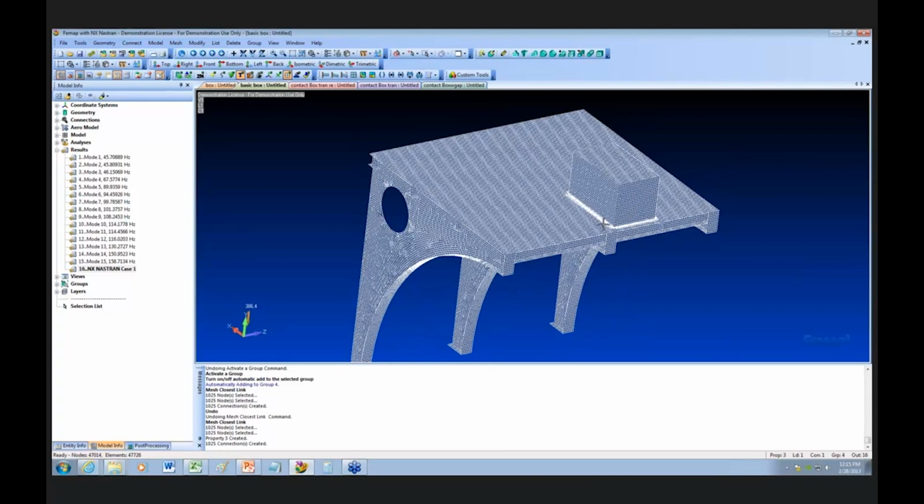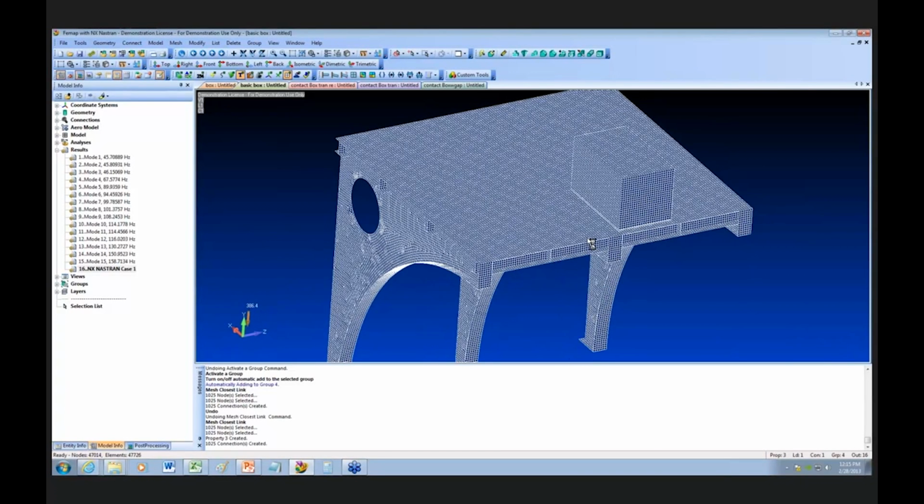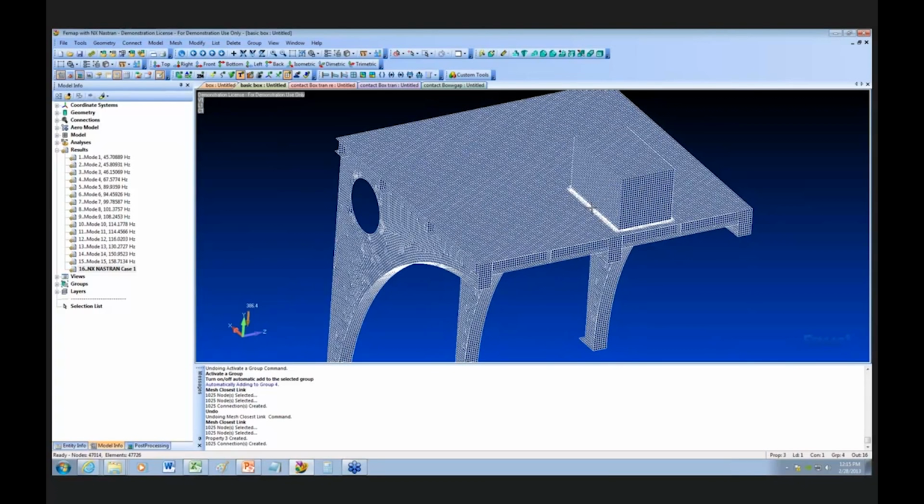At the simplest, since I'm running a transient, it is dynamic, I want to make sure that there isn't any interaction between the box and the frame via the springs. I want the frequency to be way out of range of the other frequencies, so I have pretty much a rigid contact here, but there'll be flexibility with the springs. So how do I do that?